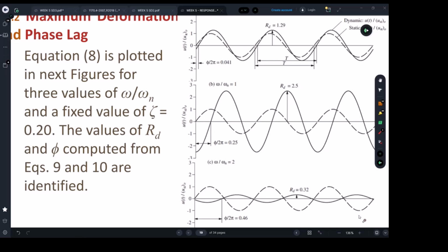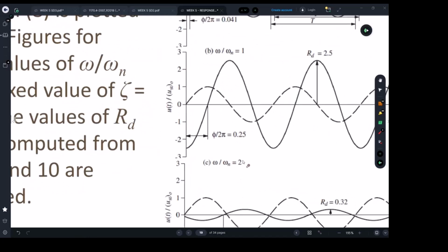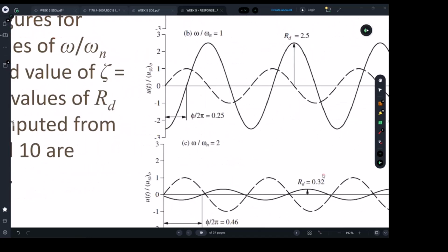And what they do, they try to play with the stiffness of the structure, because a building near a tram line has very high stiffness. And usually if you make sure that the stiffness will result in this ratio, then the dynamic response will be very, very small and it won't be a problem.